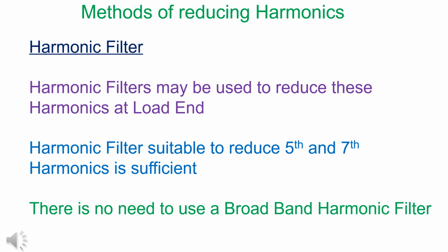Harmonic filters may be used to reduce these harmonics at the load end. Harmonic filters suitable to reduce fifth and seventh harmonic is sufficient. There is no need to use a broadband harmonic filter.